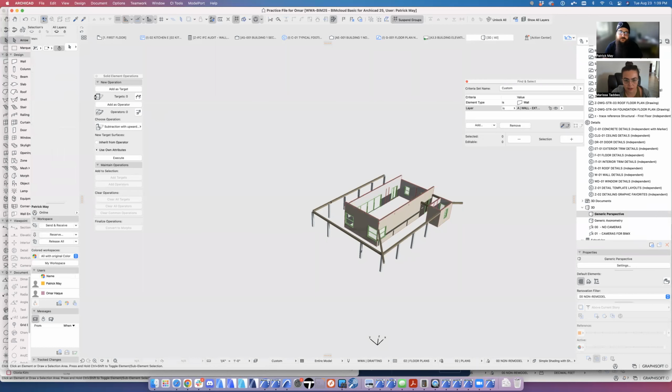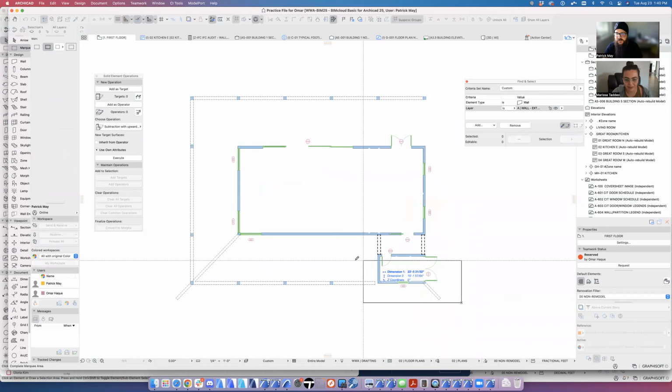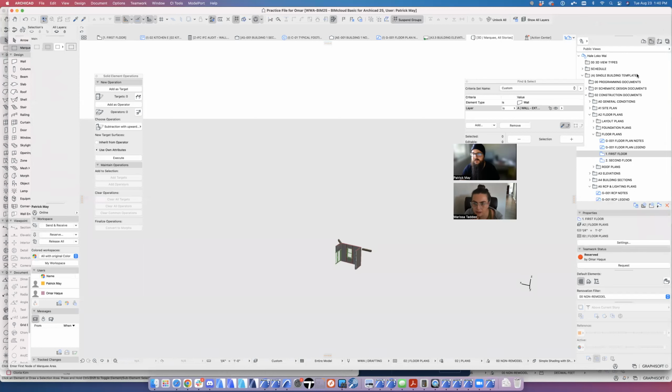What else? The marquee tool, the bold marquee versus the light marquee. One of the biggest things, especially when you're working on interior elevations, because so much of the interior elevations are live to the 3D model and you get into these really tiny spaces. Having a bold marquee and isolating that out gets you access to those rooms to really edit and manipulate. And then additionally, don't be afraid to save extra views.